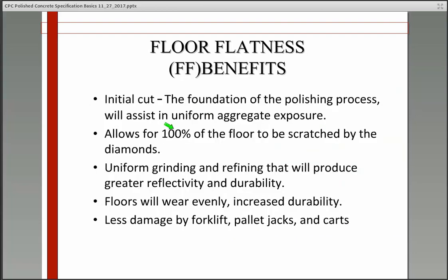Flatness benefits. Some of the things that are very important, why they need to be spending time thinking about this is that initial cut. That initial cut is the foundation of the polishing process, just like the foundation when they're building a building is the most important thing they do in order for their building to come out uniform. With this initial cut, it is the most important with a flat floor in order to get a uniform aggregate